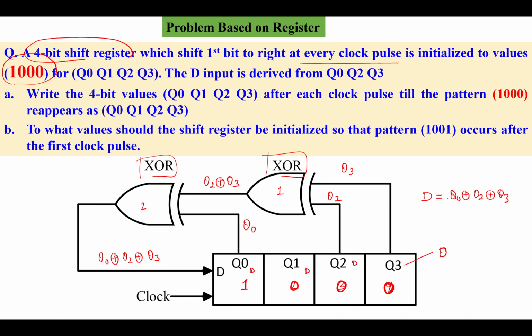Now all the data are there. We have to apply the clock and shift the data. But the question is how many times we have to shift, that is, how many times you have to apply the clock to get the same pattern in the flip-flops.